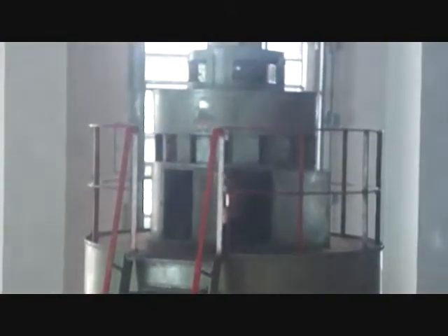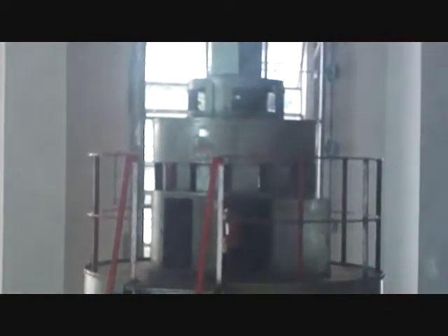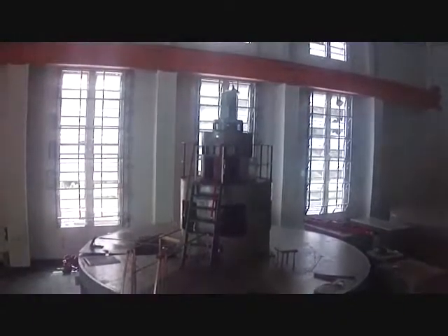Generation. Generators. One of the essential components of power systems is the three-phase AC generator known as synchronous generator or alternator. Synchronous generators have two synchronously rotating fields. One field is produced by the rotor driven at synchronous speed and excited by DC current. The other field is produced in the stator windings by the three-phase armature currents.